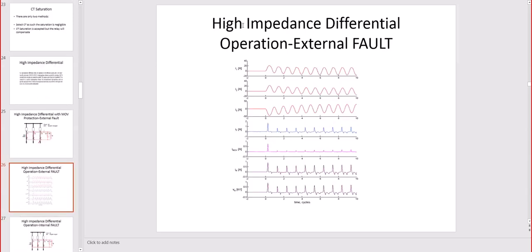So that's the typical arrangement for high impedance grounding. High impedance differential. And here you can see the currents I was talking about. So this is the current, you see the three-phase current, and then you have the total current, the MOV when it's actually conducting, and the relay current you see is totally non-sinusoidal, and then the voltage is the last one, which shows you a lot of harmonics if you want, but really we talk about in protections not that much of harmonics.